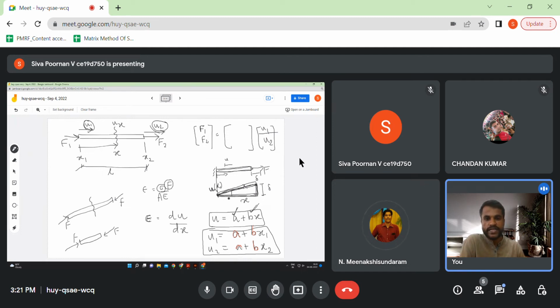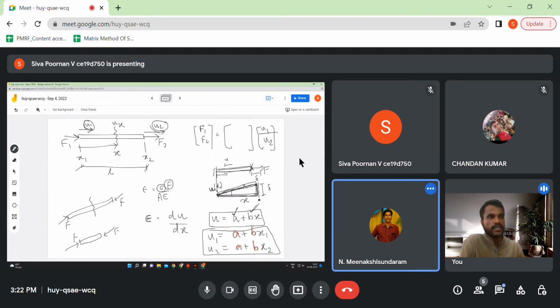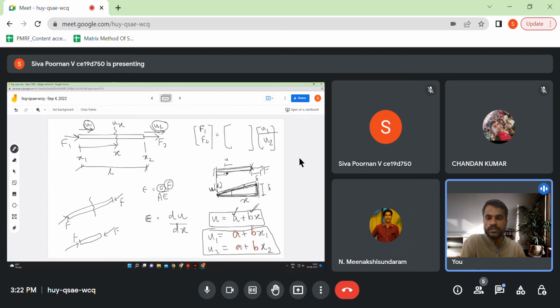How do we plot, right? That value will increase, and here the displacement at this point will be maximum. So it's just an elongation problem. It is not vertical deflection, it's a horizontal deflection, right? That is why the displacement at this point is delta, which is the same as what we are drawing here. This is just displacement of x, not the deflected shape. It's just the plot that shows the displacement with respect to span. Is it clear now?